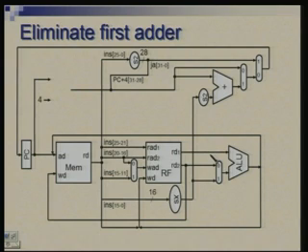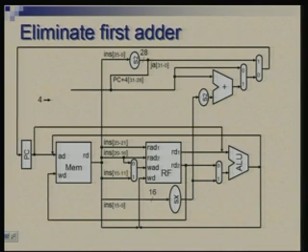It was getting two inputs, PC and 4. So, the input coming from PC is brought in to this point of the ALU. Okay. So, this is a new connection, and the second operand 4 will be brought to this multiplexer.